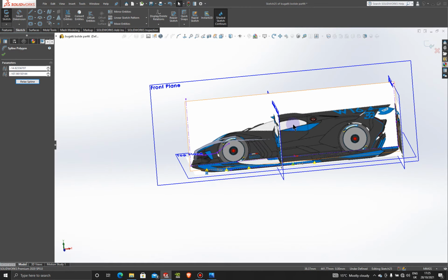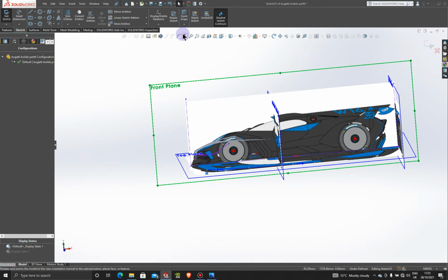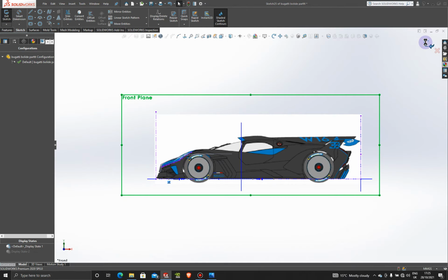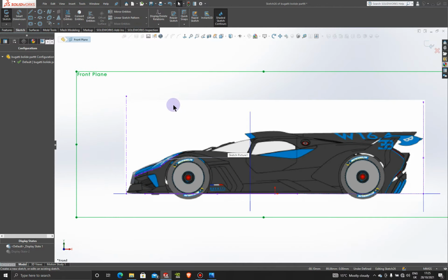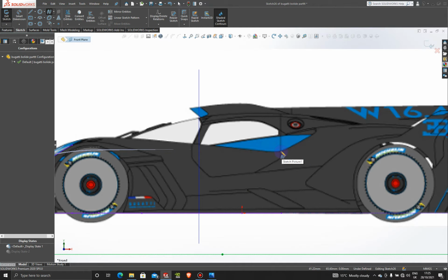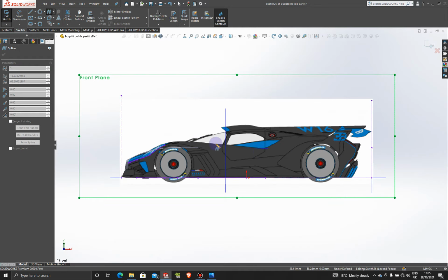And now let's try and add our second curvature from this side. Okay, let's exit this sketch. And let's create that sketch here. So spline. And then we're gonna start from maybe a little bit more further back here.